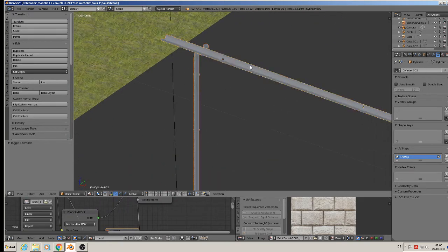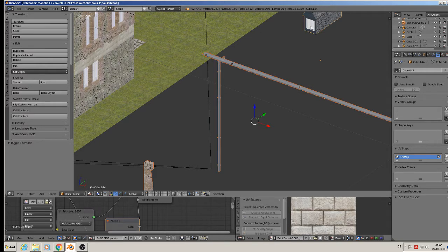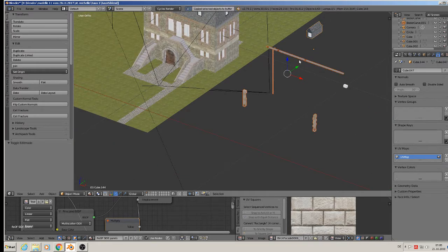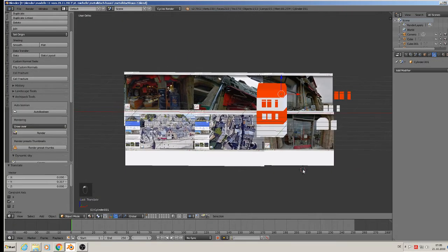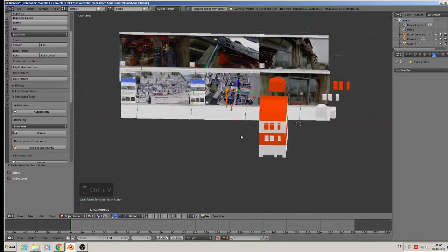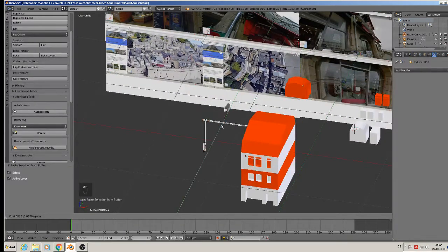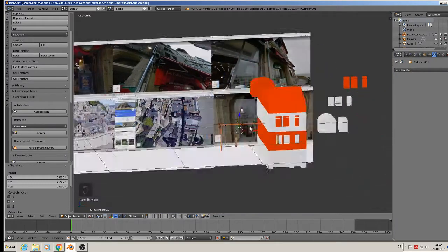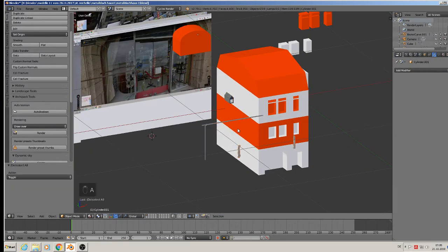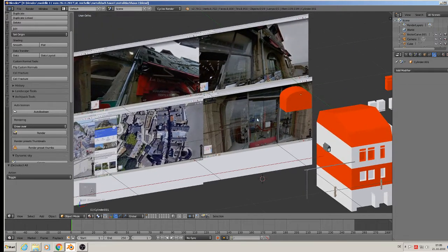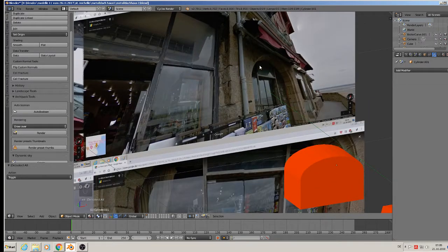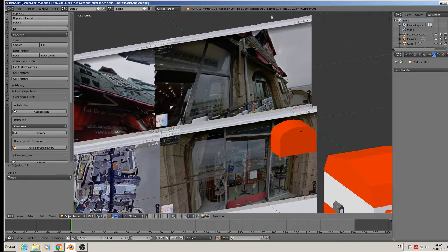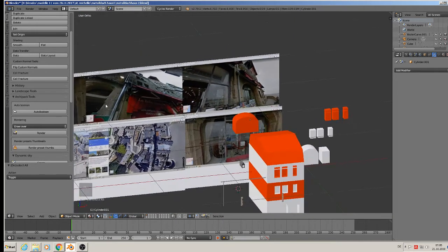So we can take them with us. Control C to copy from this project, go to our new project, metal roof house, and Control V to paste in. And here they are, and we can use them now easily. Good. On both sides there's this water sheet, and then these little roof tiles. Okay, file, save.